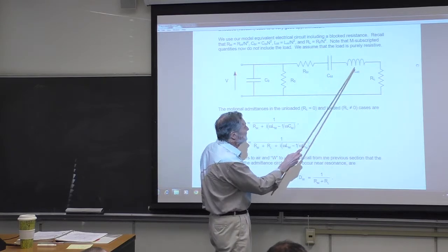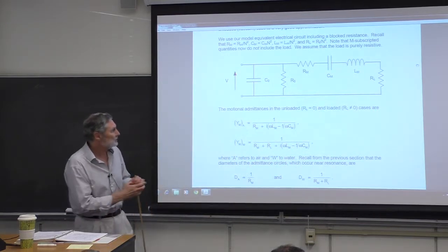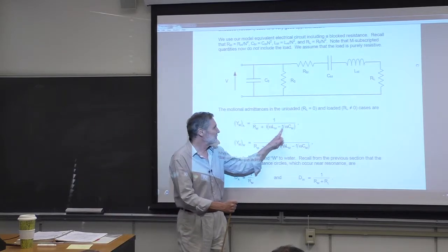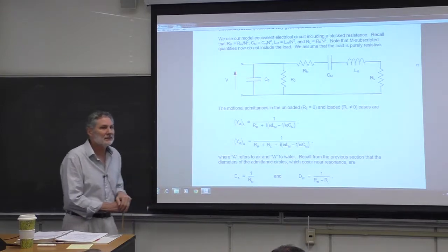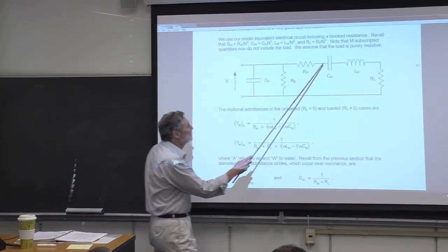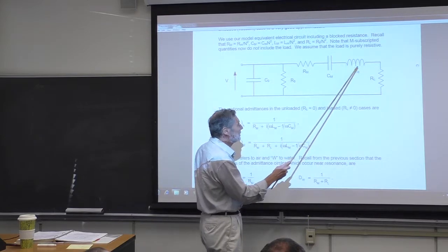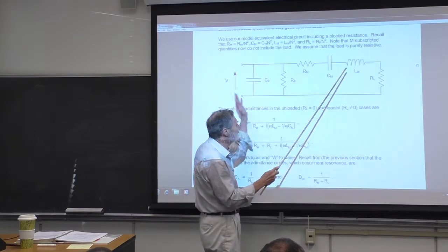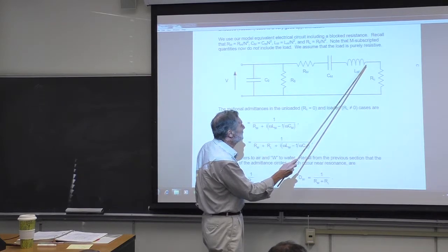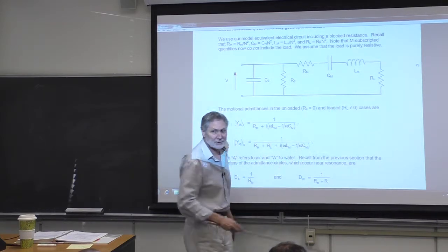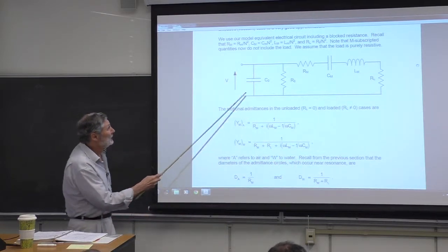And the impedances here are equal. It's easy to see that the impedances are equal and opposite. On resonance, this is 0, right? So they're effectively canceling each other out. In other words, the potential difference across here is always, through one cycle, equal and opposite to the potential difference across there. So this is effectively just a short. And now we have a very simple circuit.